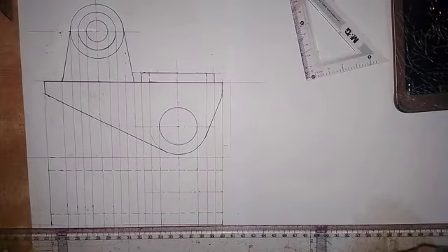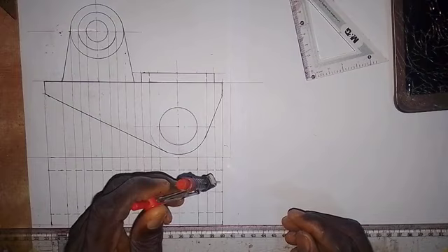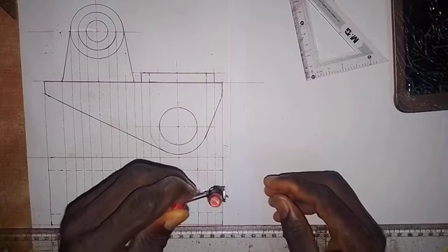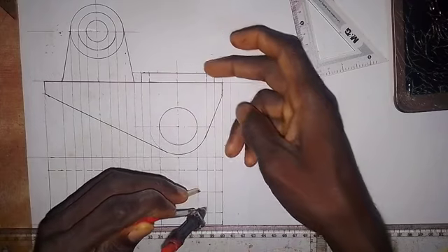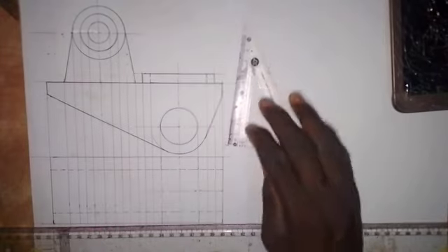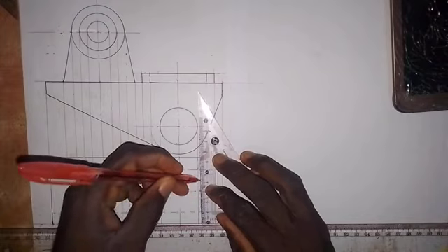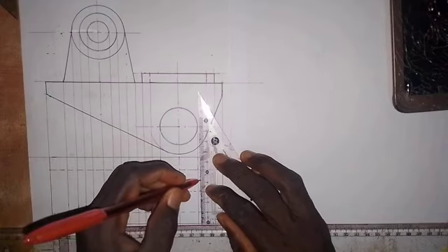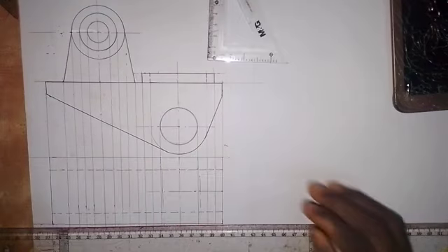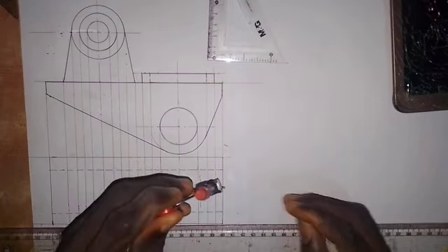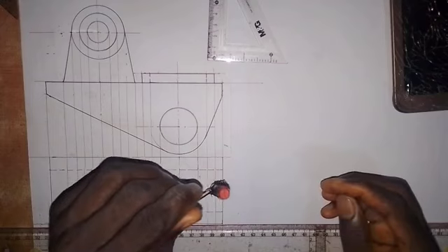So I'm going to take the compass. So put the pinpoint here at this point. Okay, so I'll put it here, and I will draw an arc. Okay, semicircle. Alright, so we took that 16 from this line, so I need to draw this line. Okay, so I'll draw it as a center line, because when we draw that semicircle, it must touch this line. Okay, so the same thing on this side, it must touch this line. Okay, so we have this. So I'm going to put the pinpoint here, and then I will extend to this point and draw the big semicircle, which goes like this.